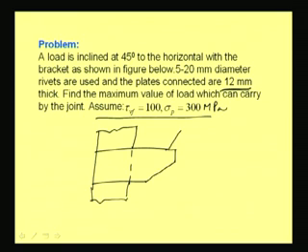Now, the load is acting at a 45-degree angle, this P. Again the rivets are given in this way, the distances are given, pitch distance and edge distance are all equal, which is given as 5 centimeter each, that means 50 mm, 50 mm, 50 mm, 50 mm, and similarly this has been given as 60 mm, this is 60 and this is also 60.